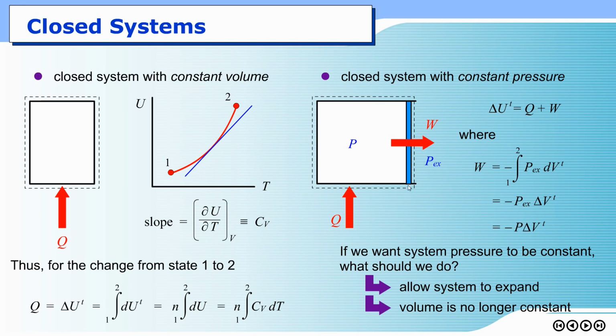By saying that this piston is under mechanical equilibrium at all times, you can also say that the process here should be reversible, right? From lecture 1b, we said that whenever the system is changing under the condition that it remains at equilibrium at all times, the whole process would be considered reversible. So in this case, we can calculate work based on the reversible path.